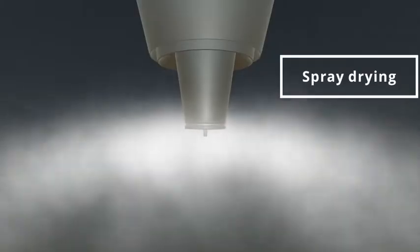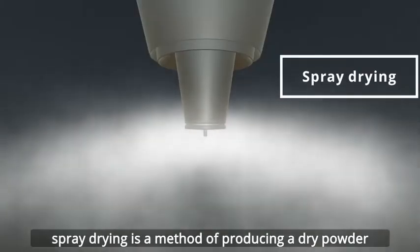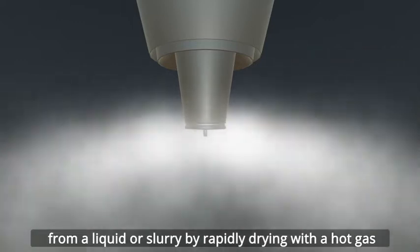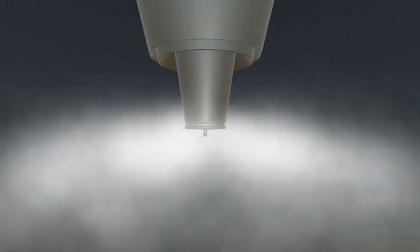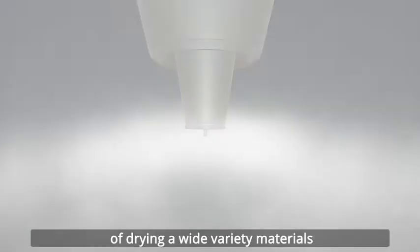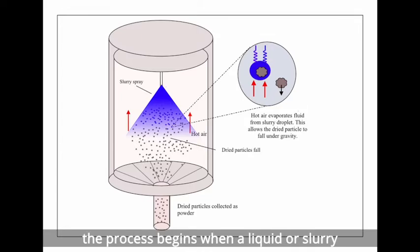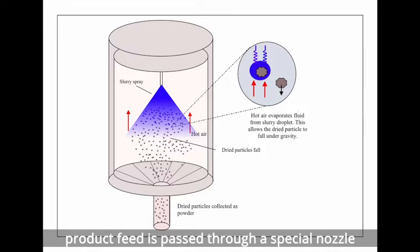Spray drying. Spray drying is a method of producing a dry powder from a liquid or slurry by rapid drying with a hot gas. This is a preferred method of drying a wide variety of materials, such as food, medicine, and ceramic powders, which require extremely consistent fine particle size. The process begins when a liquid or slurry product feed is passed through a special nozzle.